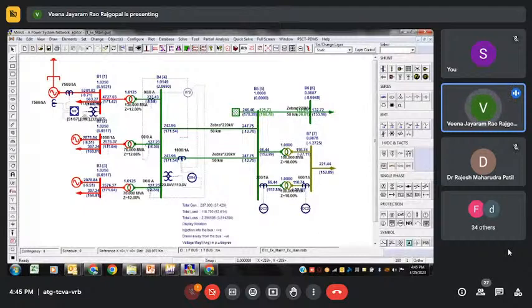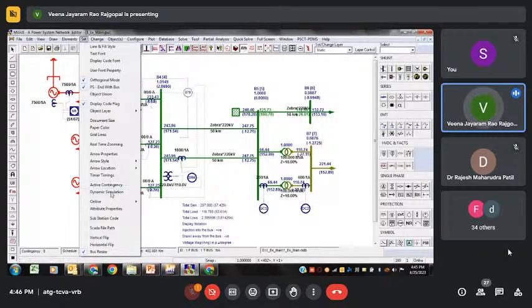There is one more small thing which I would like to show. Now the load flow is done for this. If I want to do what-if analysis, say for example, I want to open some of the things and see how, there is another option where you fixedly open the status of that. Then there is one more option called dynamic simulation.